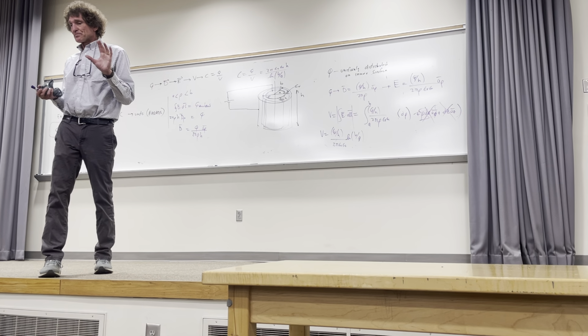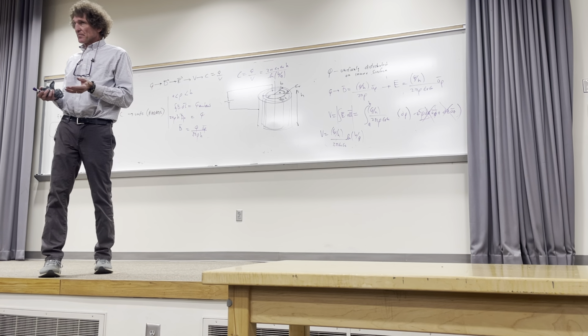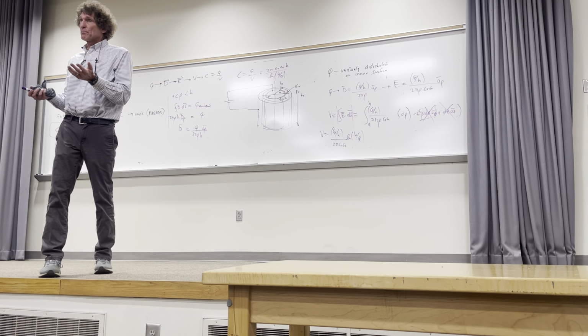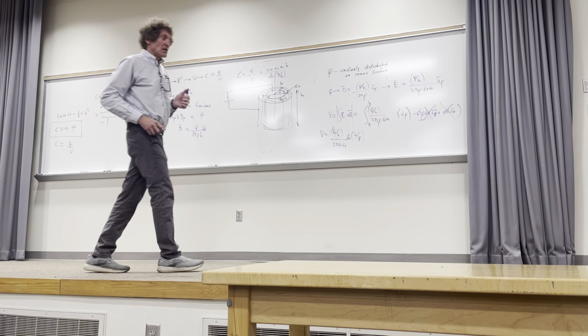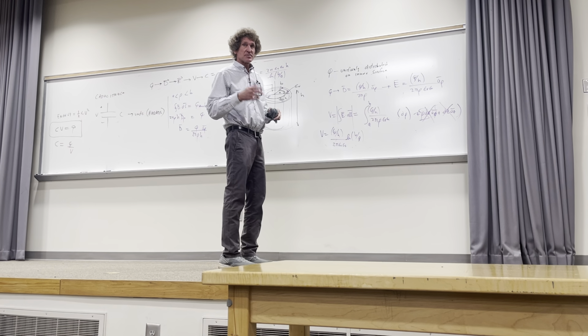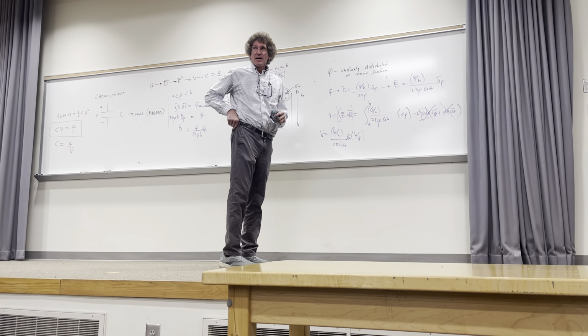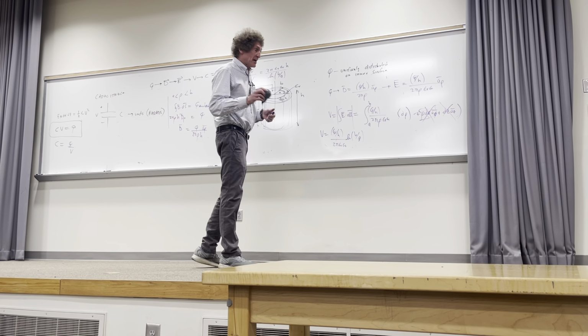But they're looking for something with a very large dielectric constant and a very large breakdown strength, and the two are against each other, because the higher the breakdown strength, usually the lower the dielectric constant, unfortunately. So these are things to be aware of. If you get a job in this industry, keep this in the back of your mind. Some of the things with capacitors you have to be aware of.